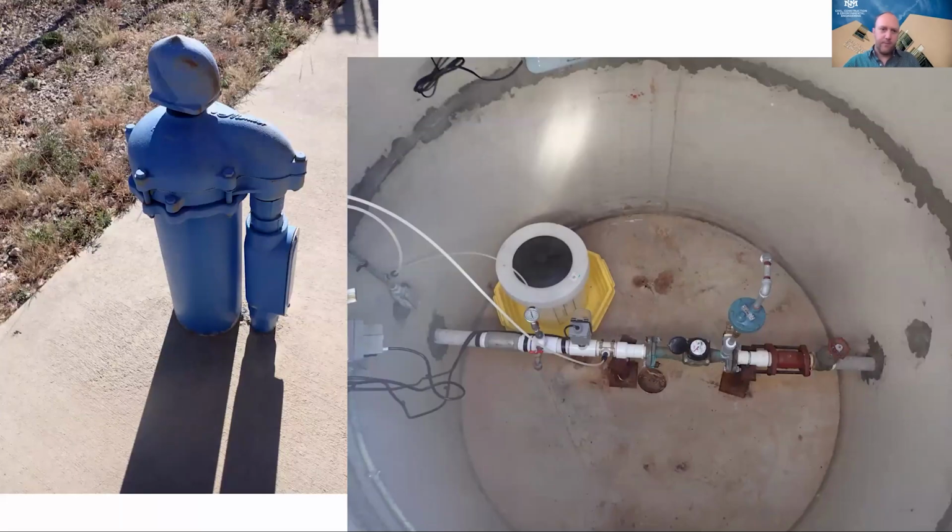And this is what that looks like. This is the wellhead, so this is what it looks like above ground. You can see that this is where the power cord is going up through this cap and then down into the well to power the submerged pump located in the well. There's a vent, this right here, and that allows the well to breathe. But as the water is being pumped up, it doesn't come up through the surface. It goes underground. And then in this example, this is where it pops out. Ironically, this is also in a pit, but this is where all of the appurtenances and the equipment along this plumbing tree are located.